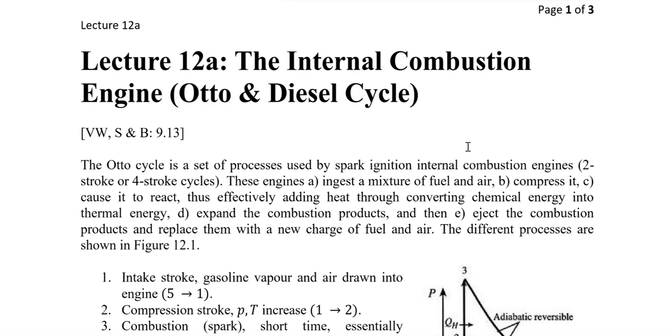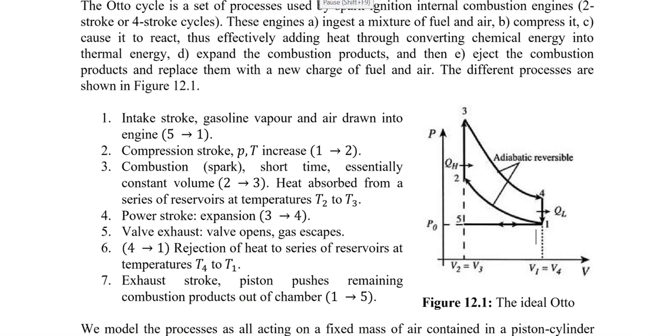The stroke is actually the displacement of the piston from the top dead center to the bottom dead center. The top dead center is the minimum volume, I would say, near the piston head, while the bottom dead center is the maximum volume that the piston can move. We have this volume known as the clearance volume, while this volume is called the swept volume, while this is called the whole volume or the total volume.